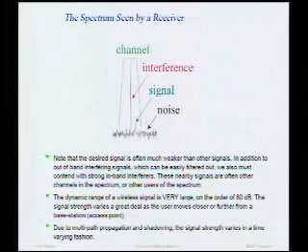Depending on the frequency of operation, let's say I'm communicating at 10 gigahertz, the wavelength's on the order of a centimeter. So if I just move a centimeter back and forth, I'm changing the phase of these different paths by an order of a wavelength, so that the phase can change and I can get a significant amount of change in the amount of signal I'm receiving. This is called multipath propagation. There's also shadowing, the fact that I could be behind a tree or behind a car when I'm communicating and all of a sudden my signal strength drops a lot, or I might be around a corner, and so on and so forth. And this is all happening in a time-varying fashion, so my receiver needs to detect the signal strength and adapt to it.